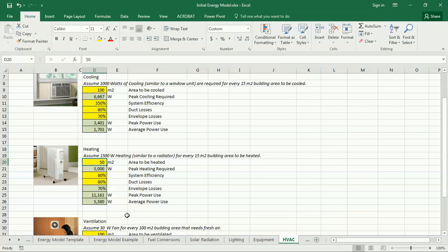And in addition, if it's a central heater, like a furnace, that's then transmitting heat through ducts, then I'm going to have duct losses. And in addition, I've got the system efficiency itself. The system efficiency for heating is pretty interesting because it depends quite widely on the type of heater or type of fuel that it's using. Furnaces that burn gas or oil or basically rely on combustion are somewhere in the neighborhood of 70 to 90% efficient.